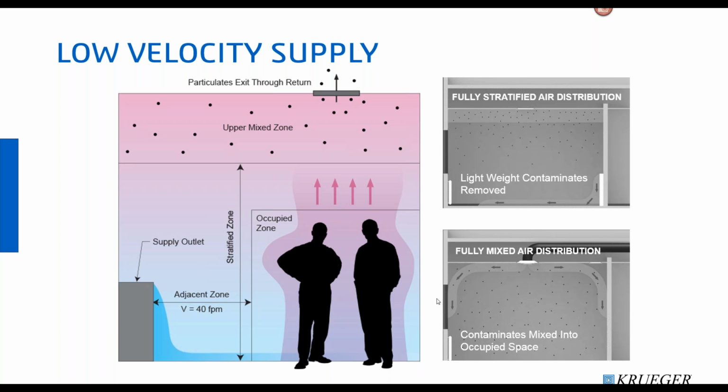So what we've created here is a supply at a location that is directly at floor level, and then we have our return at the top of the ceiling. So we're creating essentially a one-pass ventilation system. We're introducing cool air at the floor, introducing it into the room.